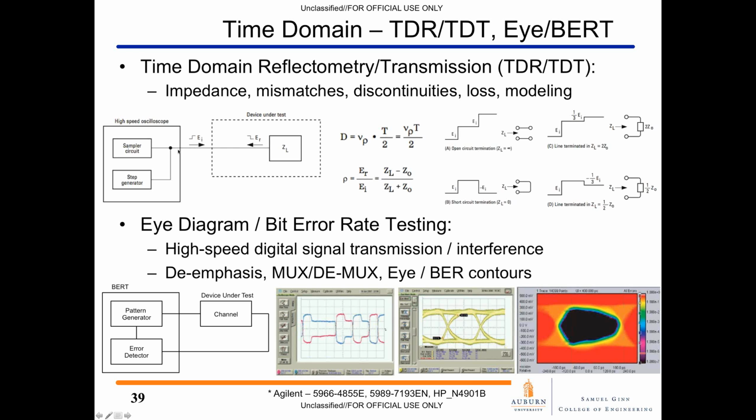This being a 50 ohm system, or set up to be referenced to a 50 ohm system, depending on the signal that returns to the scope, we can develop a better understanding of what that system consists of, or what the device under test consists of. So for example, if we know the velocity of propagation, we know the time to some transition, then we can figure out where along that transmission line or cable there's a discontinuity. We can also look at the reflection coefficients to characterize the impedance of the structure that the signal is moving down as well.